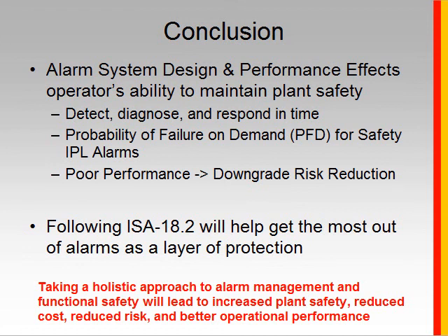We've also seen how the ISA-18.2 standard provides a lot of suggestions and recommendations on things we can do to help get the most out of the safety IPL alarms and minimize their associated PFD, and also make sure that the risk reduction is actually delivered in practice.